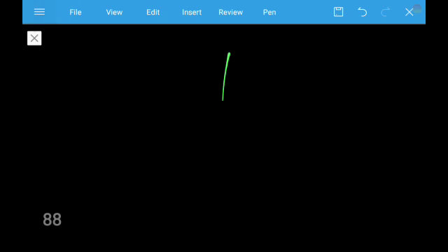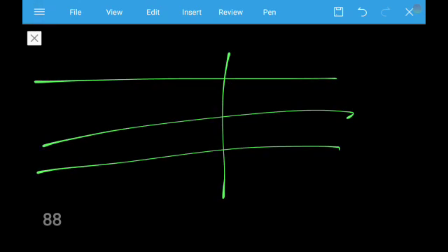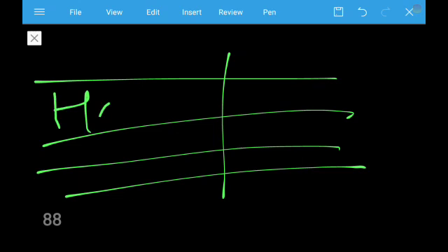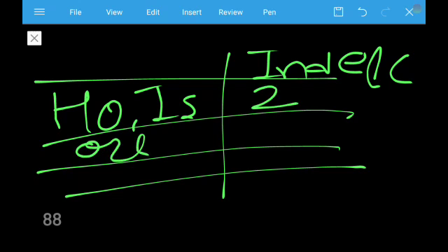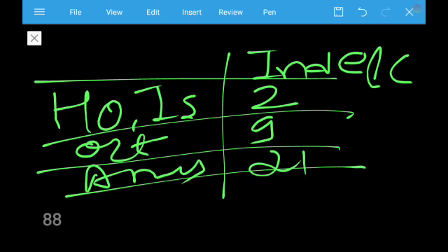And here it should be noted that for a homogeneous and isotropic material, the number of independent elastic constants is 2, for orthotropic is 9, and for anisotropic is 21.